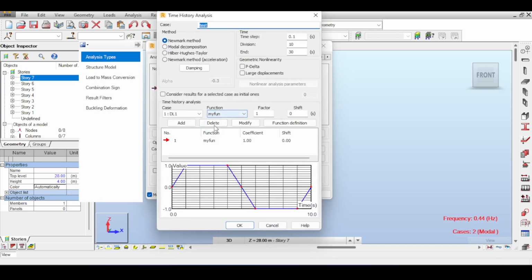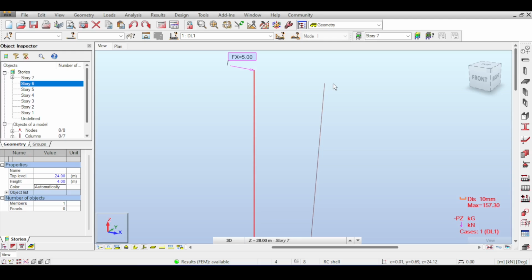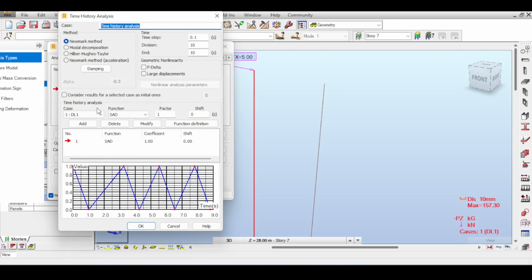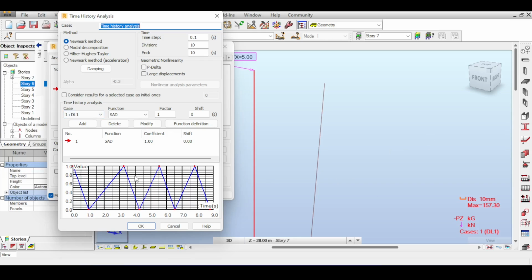So if I go to parameters right now, Autodesk Robot actually had a bug, and it took me far too much more time than I really want to admit, but I tried my best to simulate what happens if we pulsate a force using time history. For some reason in Robot, my definition for time history stopped cooperating. So I thought, okay, let's give it an initial shove, like an initial pulse at 0 seconds with the full brunt of force. And then we'll start pulsating the forces each 2.27 seconds.